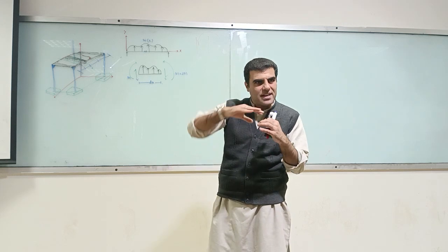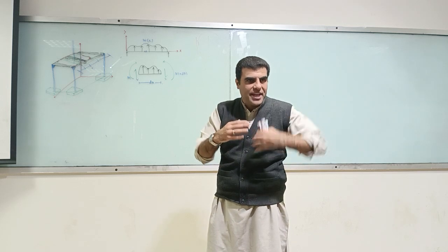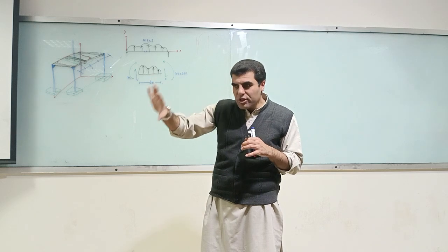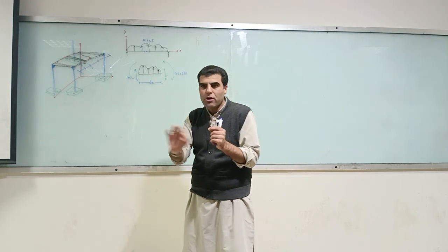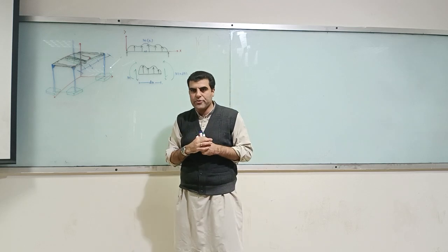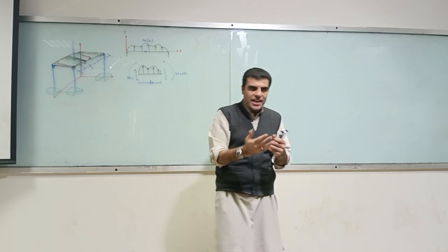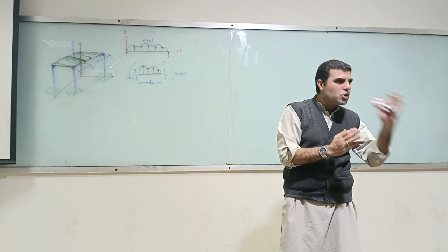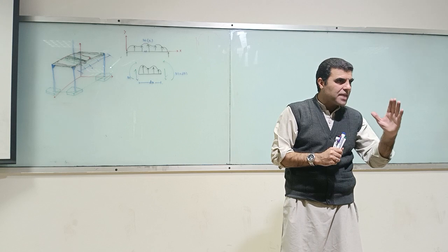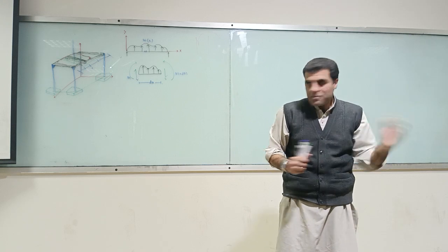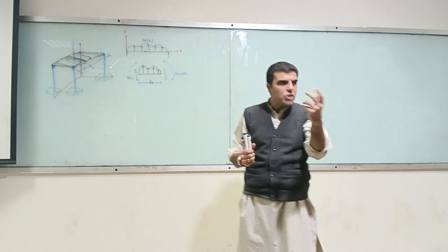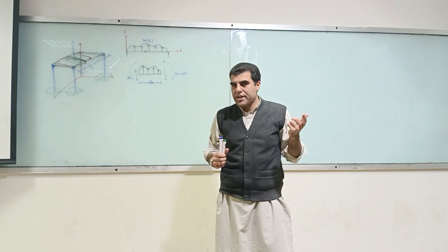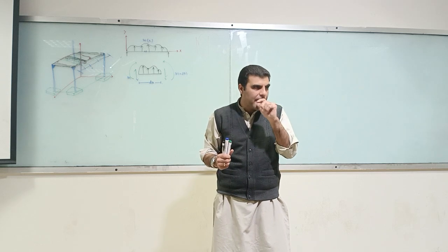So we want to avoid that, it's not possible. We want to have an intuitive understanding of the trend which is normally followed, so that we follow that trend and quickly draw our shear force and bending moment diagrams. That's why the relation between the applied load, moment and shear is important. We don't want to find out shear force and bending moment at each and every point. There are infinite points in between. So we just want to find out the trend, and we follow that trend and quickly draw our shear force and bending moment diagram. That's what our aim is.